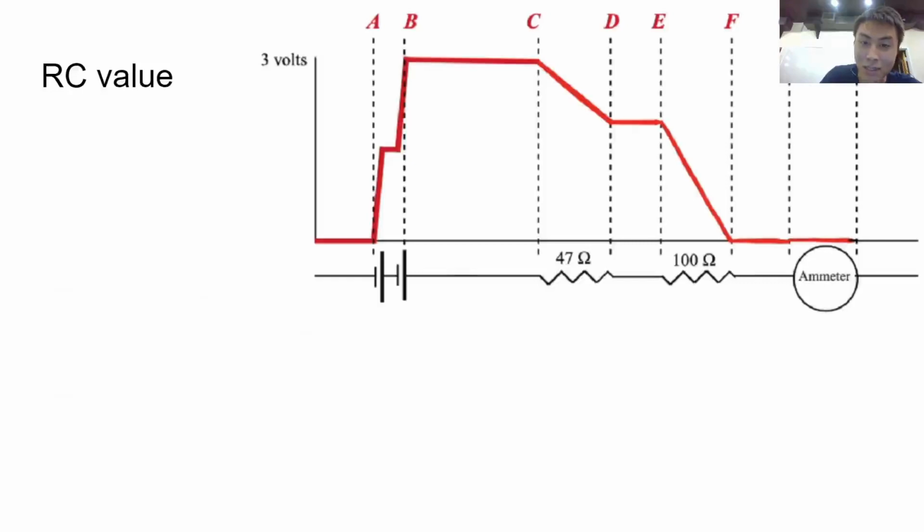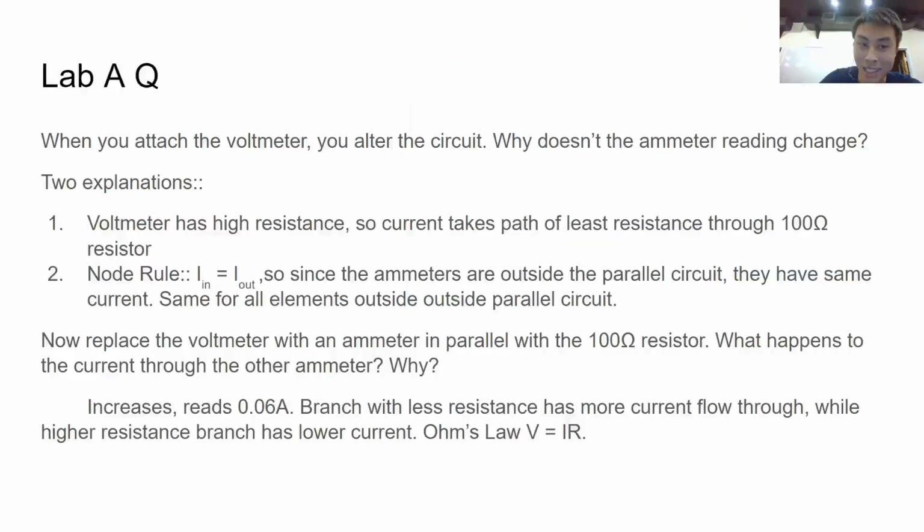Now, the values are given on this plot, where you could see the 2 batteries. They increase volts, because that's kind of what a battery does, yes. Now, once we hit our first resistor and second resistor, you can see that our voltage drops. That's because of Ohm's law, where V is equal to IR, and since current is the same, you could say that if a resistance increases, then your voltage would decrease. And of course at the end we get 0 because of the loop rule, where we see that the total summation of voltage is 0 at the end.